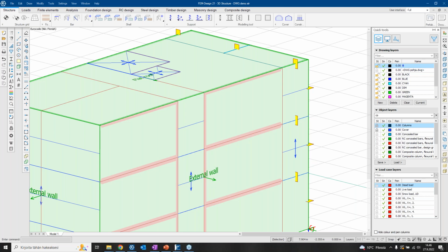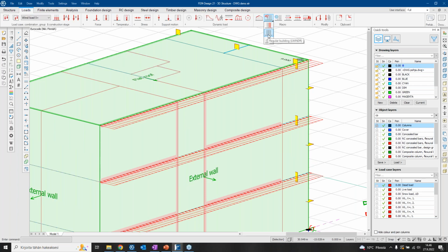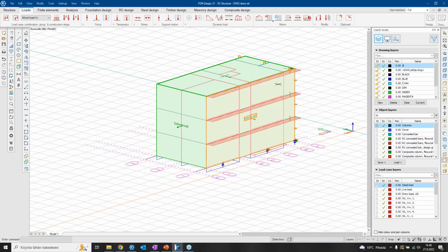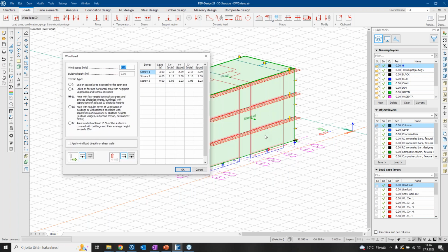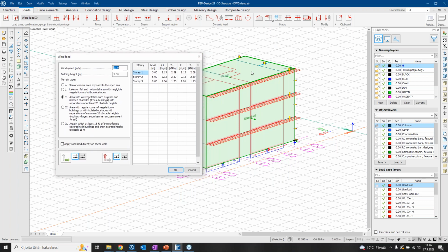When we are using the regular building, don't we need to cover regular building? No, you don't need a cover then. It will detect the slabs or the horizontal, vertical structures and automatically generate the wind on them. So you don't need the climate load panel or the cover.